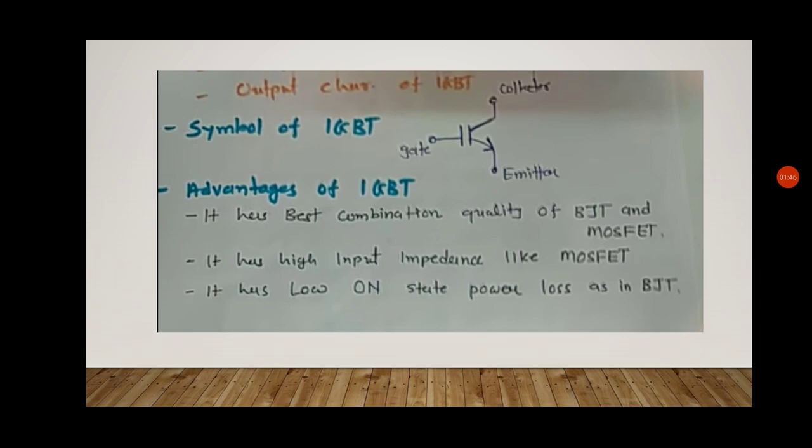The insulated gate bipolar transistor IGBT combines the insulated gate technology of the MOSFET, which is the insulated gate portion of the name IGBT, with the output performance characteristics of a conventional bipolar transistor, which justifies the second part of its name.